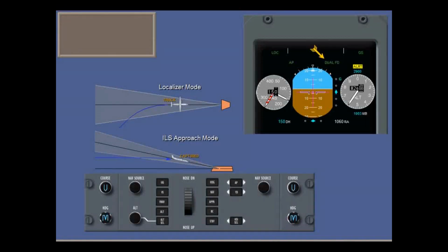If everything is normal, with the EFIS ADC and attitude heading source selectors at norm, with both VOR lock receivers tuned to the same localizer, when you start to track the localizer and glide slope at 1100 feet, verify that you're in the Cat2 dual FD submode.